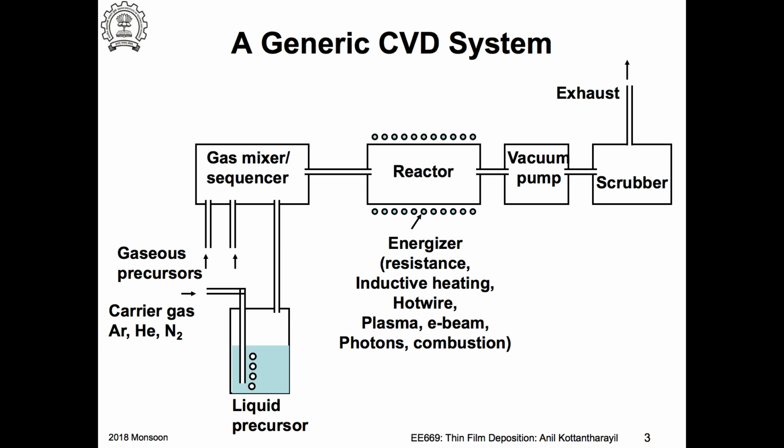So, you don't want to use oxygen, of course. Oxygen will then react with this and then create maybe an explosion or a fire. So, you would use something like argon, helium, nitrogen, okay. Nitrogen is fine if you are using resistance heating or inductive heating, or a hot wire.